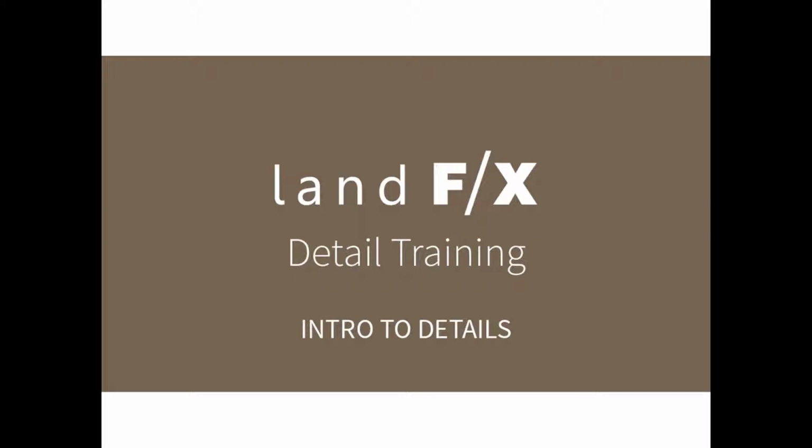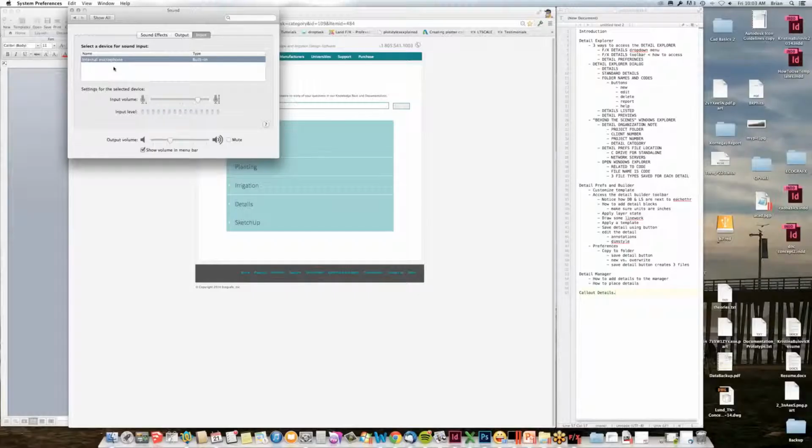Core concept number one is we are going to be inserting details as blocks. There's a huge benefit to having each detail be its own independent DWG file, and those individual blocks are placed individually as blocks. So the layers are easier to manage. The file is more portable. Obviously, to make that leap to have them not be XREFs and to instead be blocks is to some users a sea change of difference. But if you are struggling with why they would be blocks and not XREFs, I think very quickly you're going to see the benefit of that.